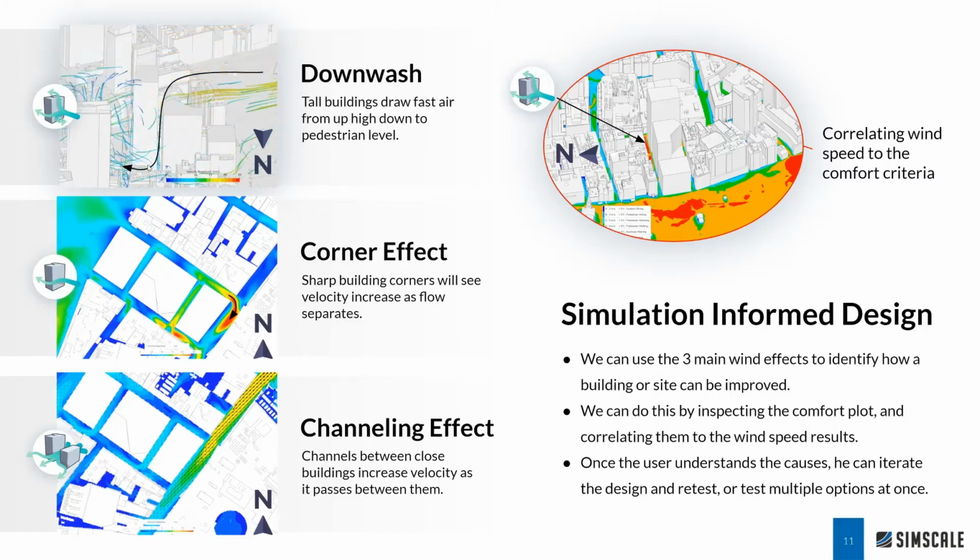We can see the cornering effect. You can see a different wind direction I've taken, that you can actually see a very dominant cornering effect happening here, where you've got high speed regions but also a low speed region here happening around that corner of the tallest building.